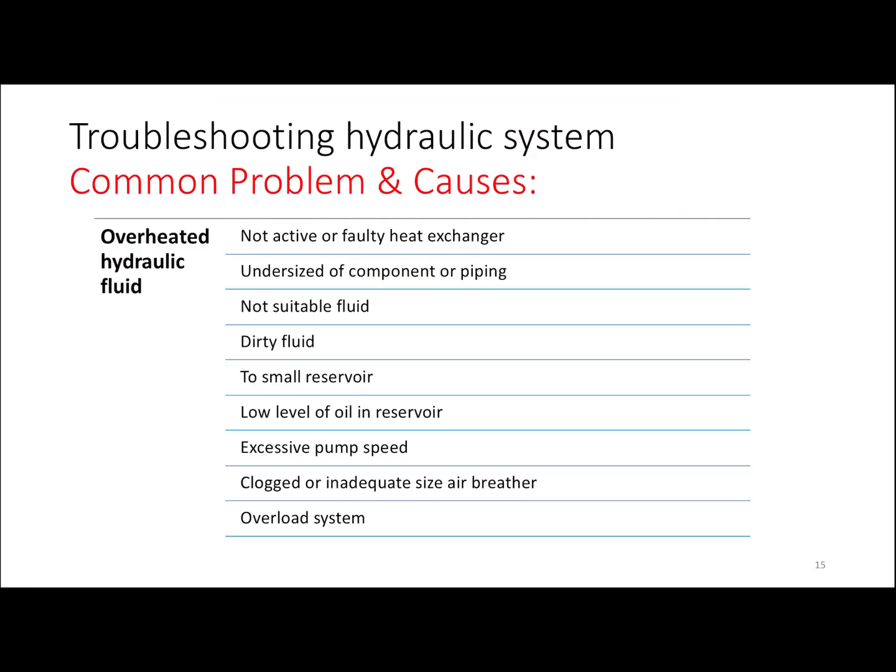Now, the next problem that can be found in hydraulic systems is overheated hydraulic fluid. This can be because of a not active or faulty heat exchanger, if there is a heat exchanger, especially if you use the hydraulic system in a cold climate. Or another big cause is undersized components or piping. Or the hydraulic fluid is not suitable, maybe too viscous or maybe too thin. Another cause is dirty fluids.